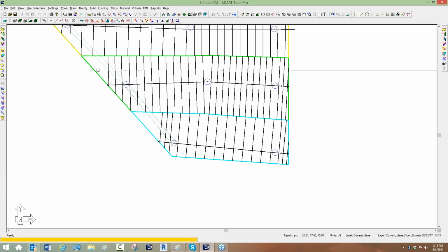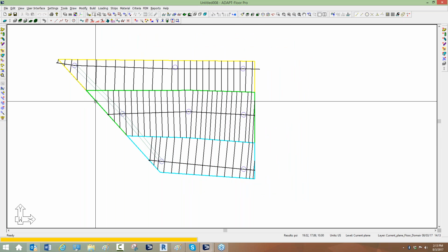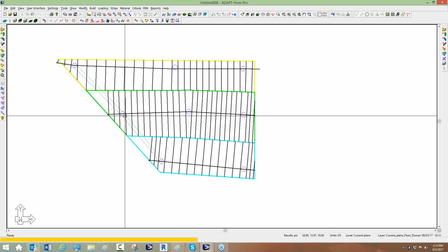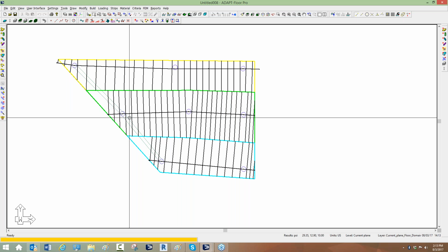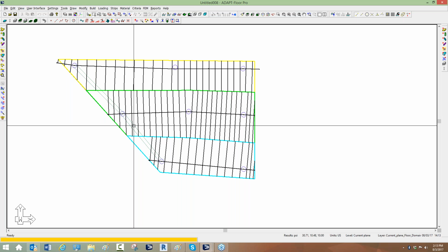What happens is we're left with these gaps. Kind of here, there's a triangular gap, and this is more exaggerated when we have, for example, a support line that might be terminated at the column. But essentially what happens is we end up with these huge gaps in a model because the program looks for the end and the start point of a support, and beams that are perpendicular or within, I think, 30 degrees from the direction of the support line, those beams technically are supports for the design strip. And you end up with these big gaps in the slab that you want design sections in.